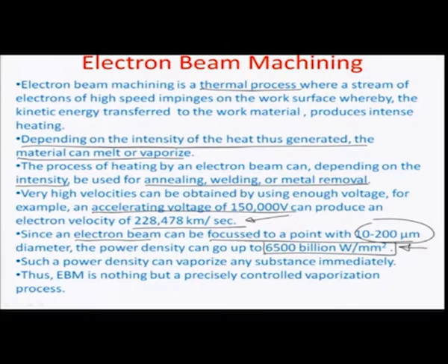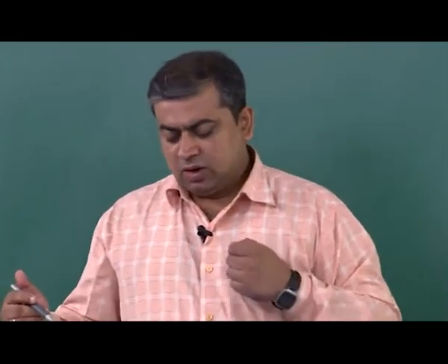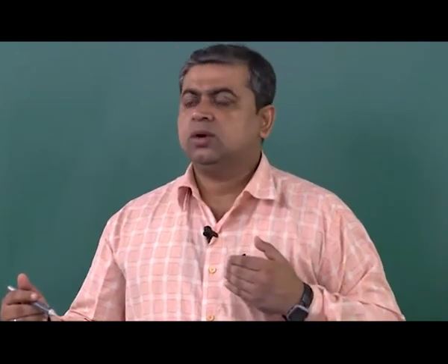Now, this kind of a power, if applied to the lattice structure or the material as such, can simply vaporize the material substantially. Okay, so it just directly sublimates, it goes into the vapor state, and if you raster the E beam over the surface, typically there is a tendency of the machining to be precisely controlled based on wherever the beam hits the material, and so as you can really super focus and narrow down the beam to a small spot, the resolution at which you can do this increases.